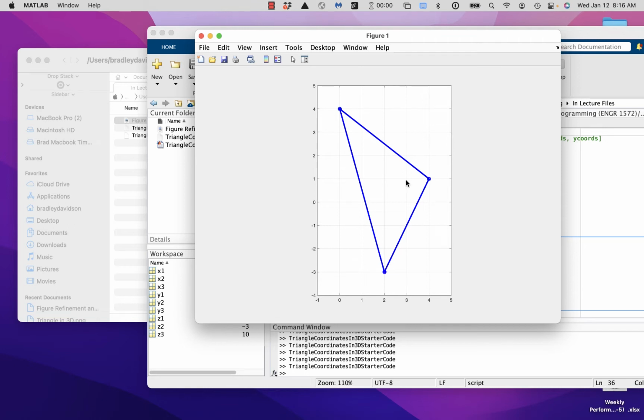And so you can see that compared to where we started, which was a distorted triangle with thin lines, and then not quite the breathing room that you needed, there's a drastic difference with some simple commands like grid on, axis equal, xlim and ylim, that you can drastically change the look of your figure and make that look a lot more refined and professional. And really, this is just the beginning. If you can imagine any type of figure, there's likely a way to get exactly what you want in MATLAB with some of the more advanced commands.